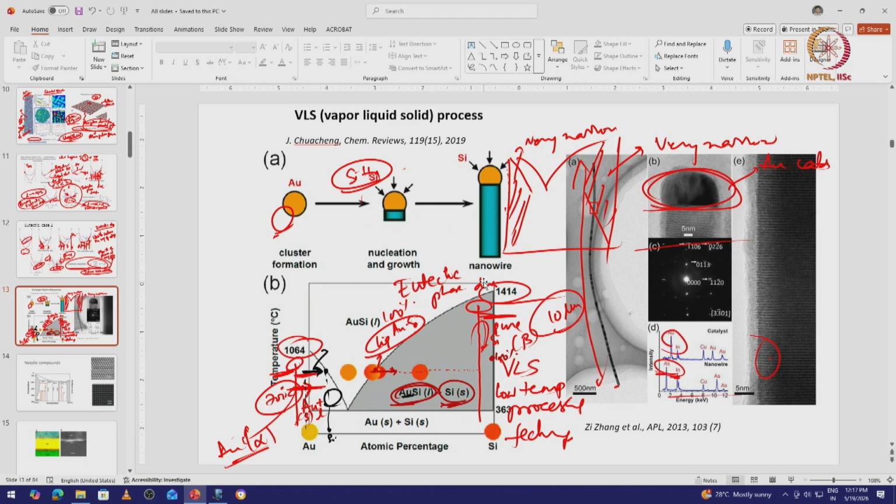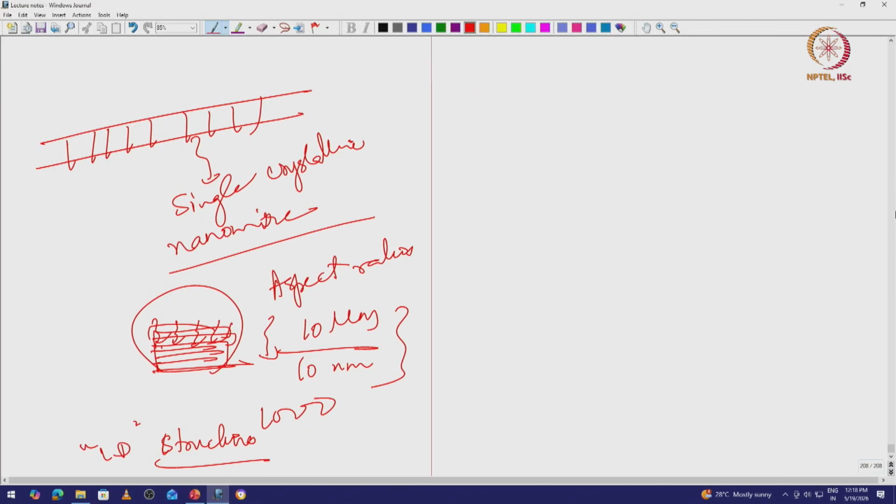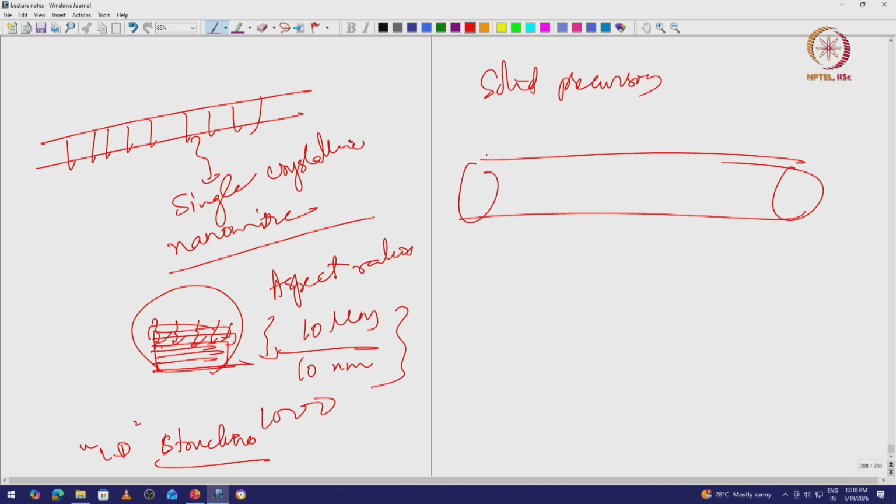If you really want to start your research, I would say start with this. I don't always need precursors such as silane, which you have to use very safely, but I don't need to worry about that. If I just want to grow indium arsenide or something else, I can just use solid precursors instead of silane, which is a gaseous precursor. For example, I am growing a material called germanium telluride, which is what is called a phase change material.